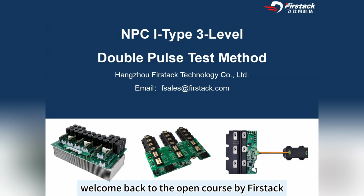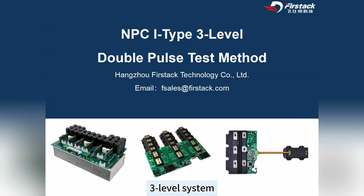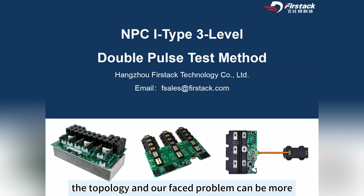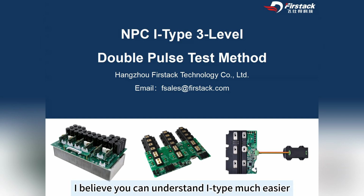Hello everyone, welcome back to the open course by Firstack. Today we continue our topic of double pulse test in three-level systems. In the last course, we already discussed the T-type topology, and this time we will introduce the I-type system. They are quite similar, I must say, but the topology and the problems we face can be more complex. But if you have already understood T-type, I believe you can understand I-type much more easily.